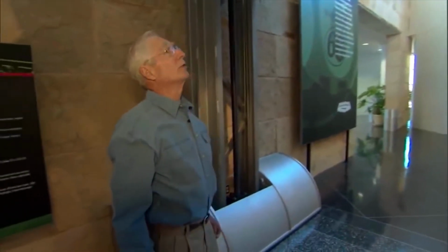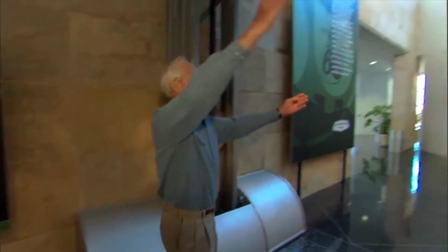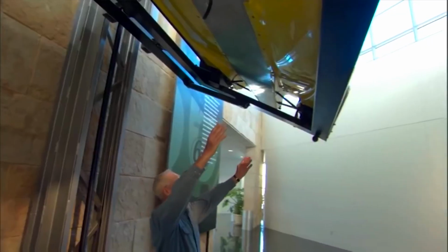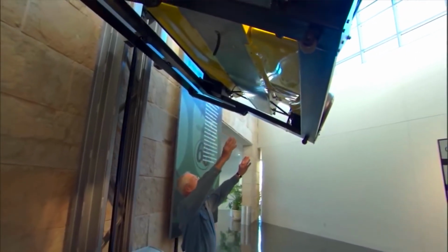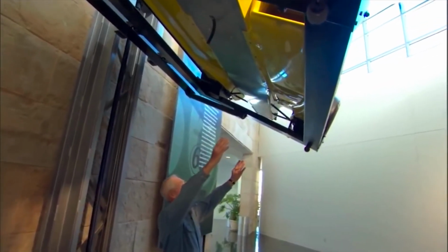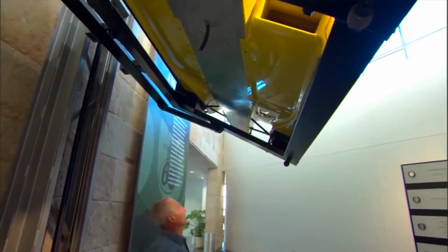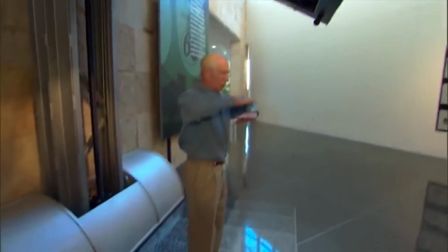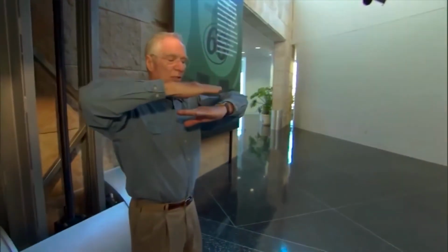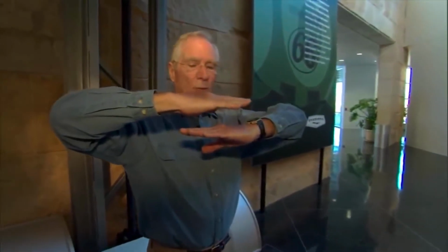So the low pressure is in the throat, and the throat is up here right in the center of the car, actually towards the rear, so that you put balanced downforce on the car. And the way you make the venturi is the shape of the car plus the road. That's what makes the venturi shape, and then the downforce is provided by the low pressure underneath the car. So they were able to win with this car.